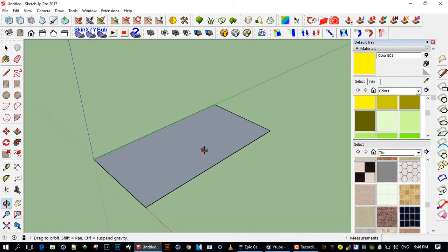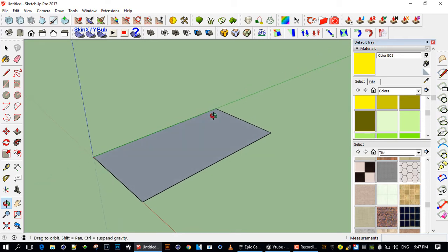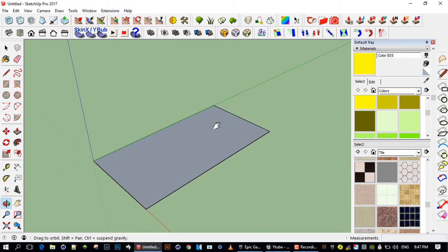The one challenge that I have is that sometimes I get models from the 3D Warehouse and take them to Unreal, and then when I render, it becomes a bit of a mess because of the light maps that get generated. There's not a second UV, and then all these blotches come on when I run it. When I take it into Unreal, it looks nice, and when I run the first build, it all goes haywire.